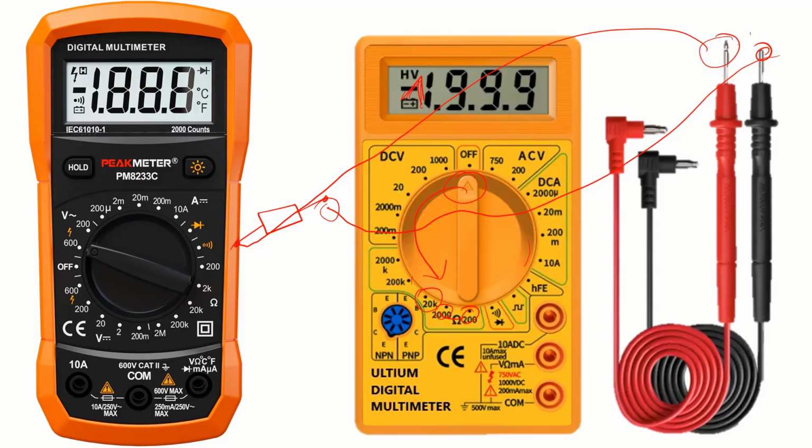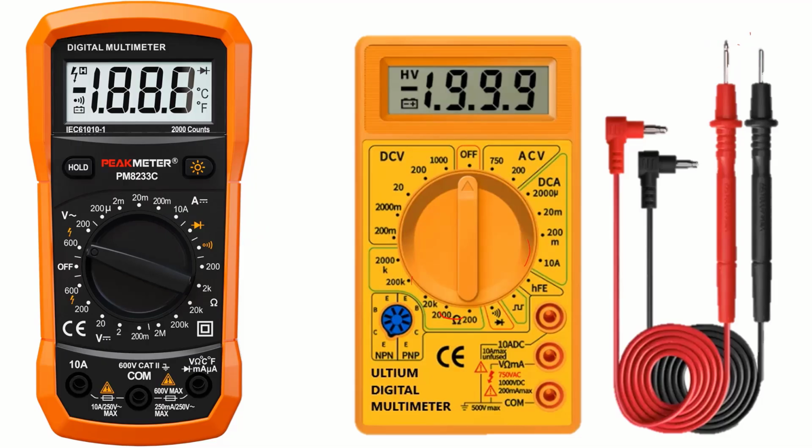That's how it functions. So it is always advisable to begin from the smallest, then you start switching to larger units. Get it? So if you want to measure current, it's better you switch. You start here. When you see 1, you go there. When you read 1, you go there. If you see a reading different from 1 here, you can collect it.